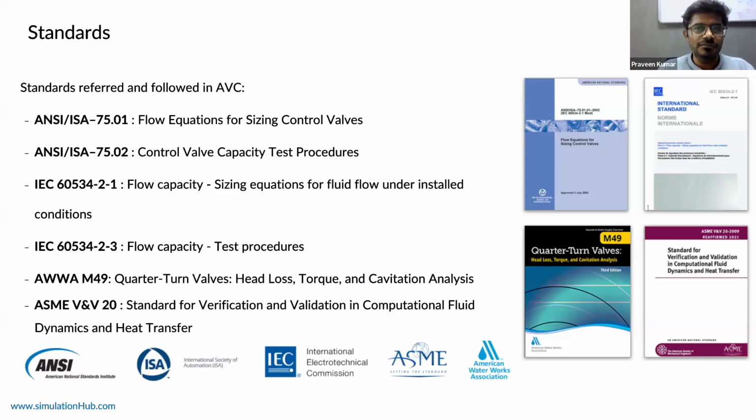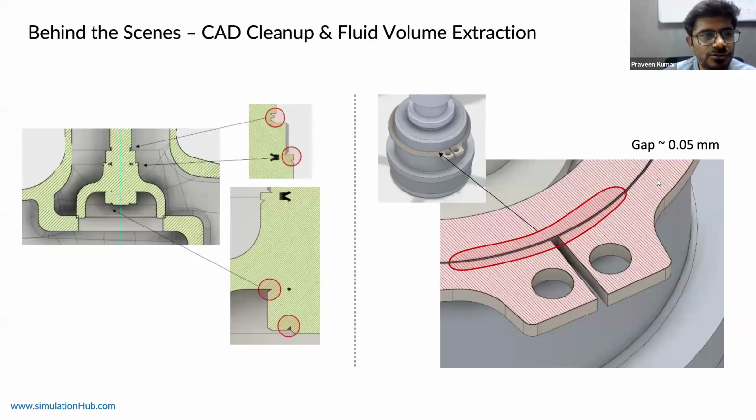The standards we follow are the ANSI ISA standard, IEC and AWWA, and we also refer to verification and validation in CFD, ASME 20. Next. So this is the behind-the-scenes part. In the CAD cleanup process, the algorithm identifies which gaps to close and which gaps to keep, and does the CAD cleanup and fluid volume extraction as well.